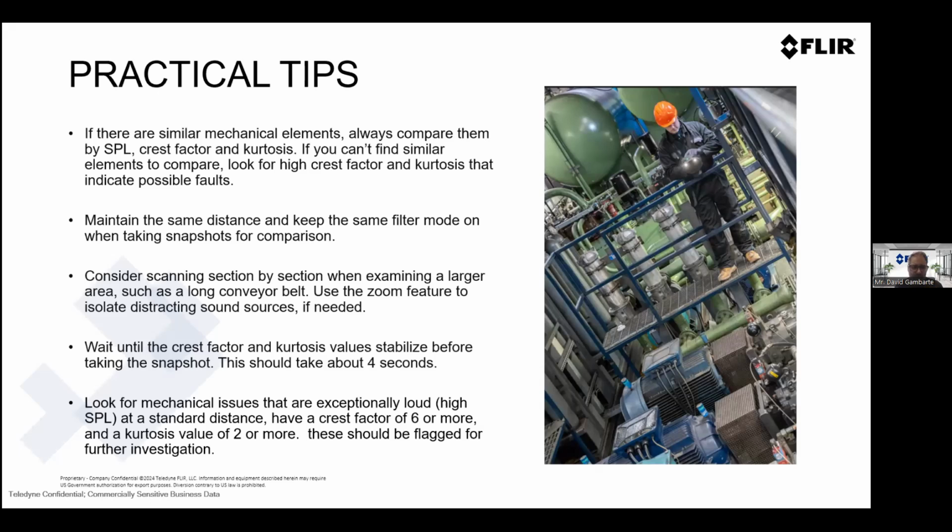Wait until the crest factor and kurtosis values stabilize before taking the snapshot. This should take about 4 seconds. So wait a little bit, and then you will get the right information on the screen. Look for mechanical issues that are exceptionally loud: high SPL at a standard distance, a crest factor of 6 or more, and a kurtosis value of 2 or more.